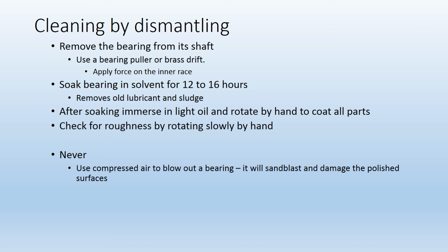And remember that for your government examination. When you want to clean a bearing by dismantling, let it soak in solvent for 12 to 16 hours. What you do in the real life may be different, but for your examination, that's the right answer.